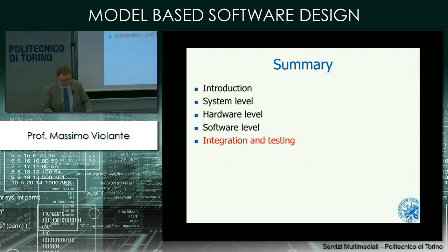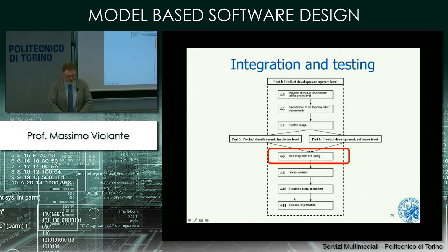Last step is where you bring together the software that you wrote with the hardware that you designed. So it is here. Here you have to verify whether your software stays nicely on your hardware. Why you have to do that? Well, this is because the software and the hardware are independently developed. Once you write your software, the hardware can be still in design. So you don't have the chance of doing all the testing activity that are required during the software development phase on the real hardware, because you may not have it.